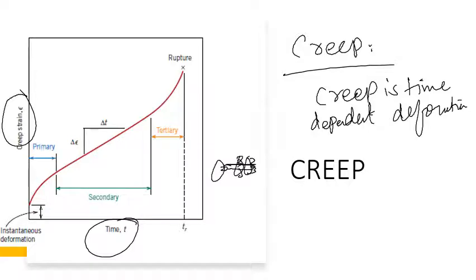They will apply a constant load on this shaft. Apparently it is below the yield stress, but these stresses act for a very long time. So for a very long time, they will deform the shaft, and this deformation is called the creep strain, right?